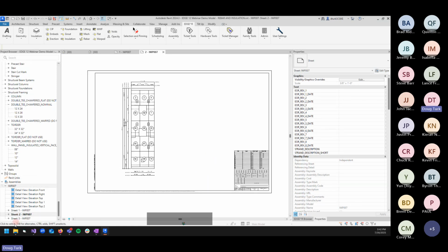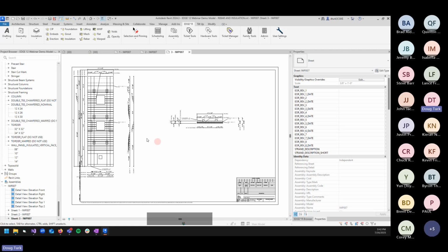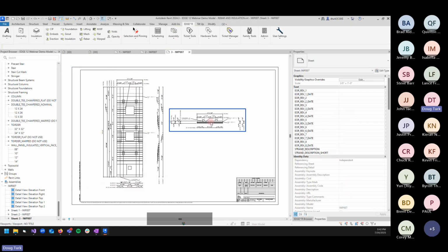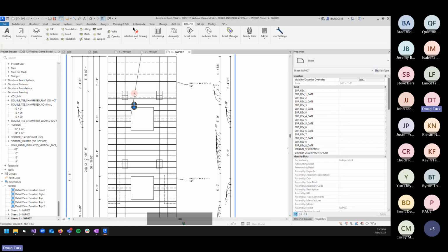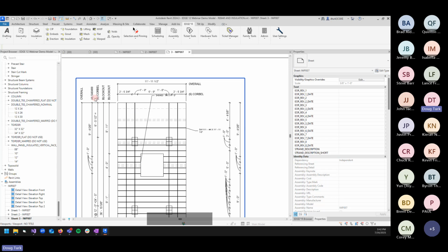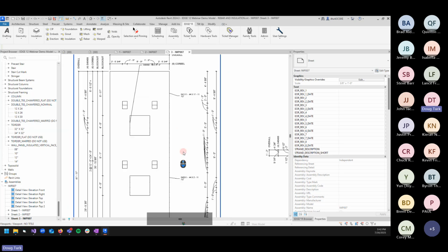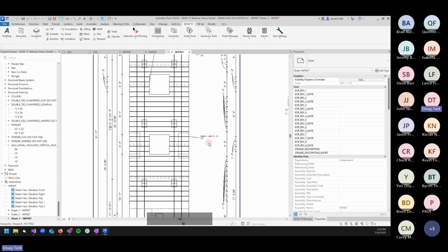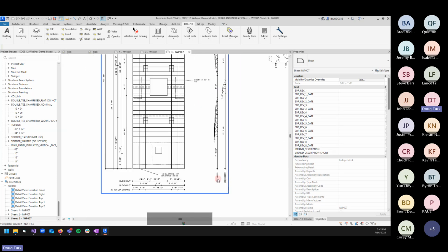Okay, so that's probably it for the insulation sheet. Let's move on to the reinforcement sheet. This one is reading out the location of strand, as well as the location of the various straight bars in the panel. What you're going to see here is actually dimensions pulled to those, as well as counts.